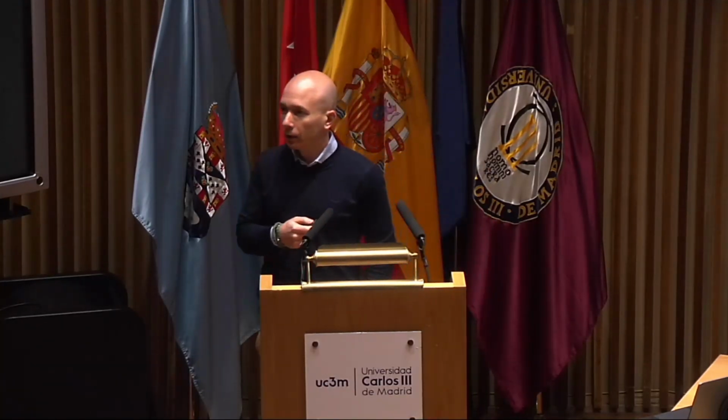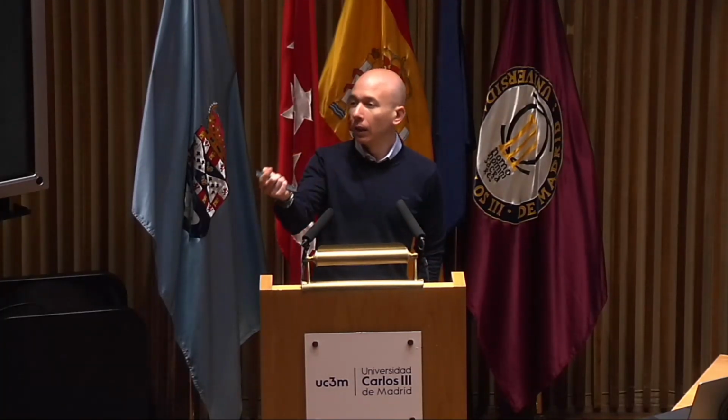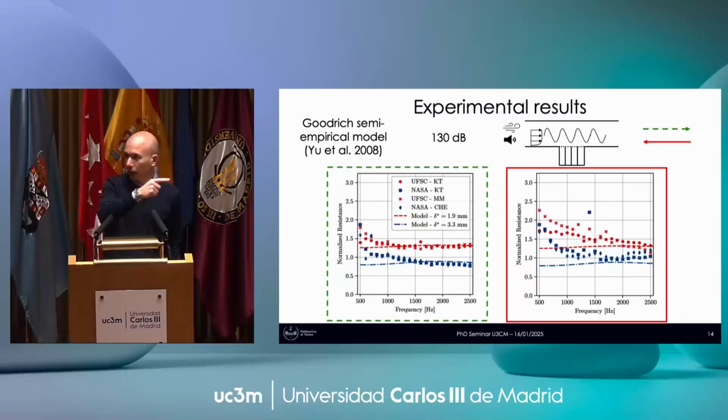We saw that taking the same data and using the codes from Brazil, that point doesn't appear. And here you're presenting the normalized resistance that is only attributable to the liners. You already subtracted the one of the tunnel. Normalized means divided by the impedance of air. That's what we name as normalized. Okay, cool. Interesting. Thank you.